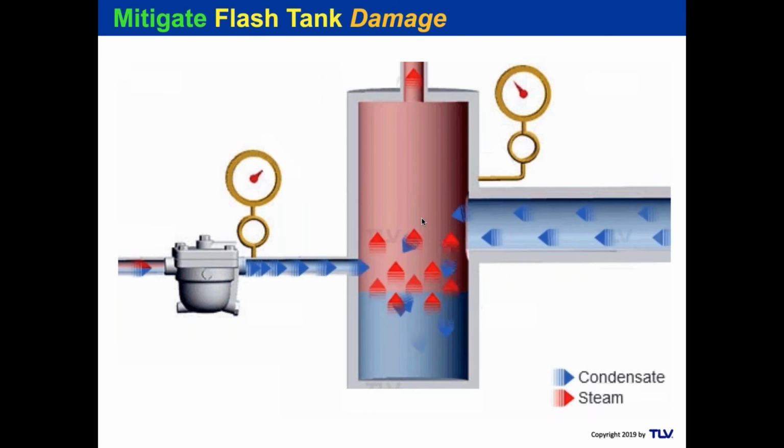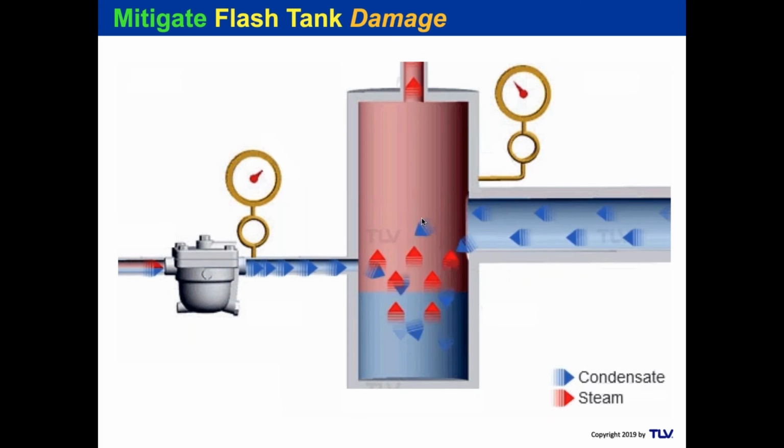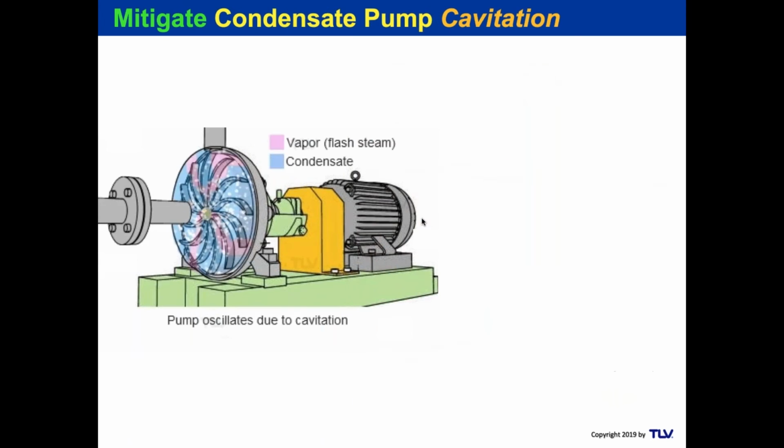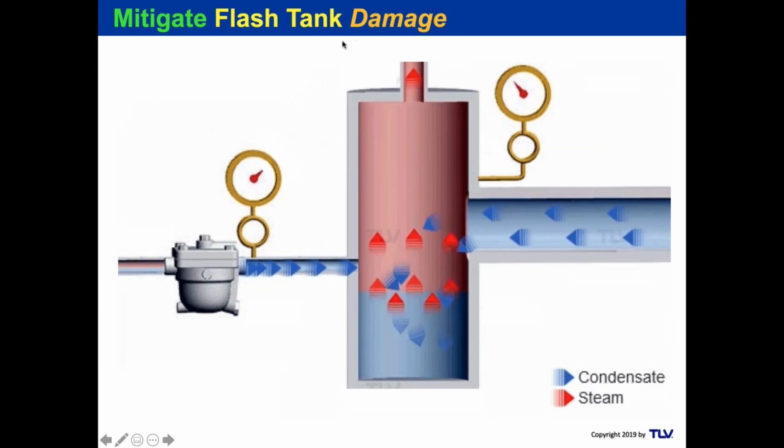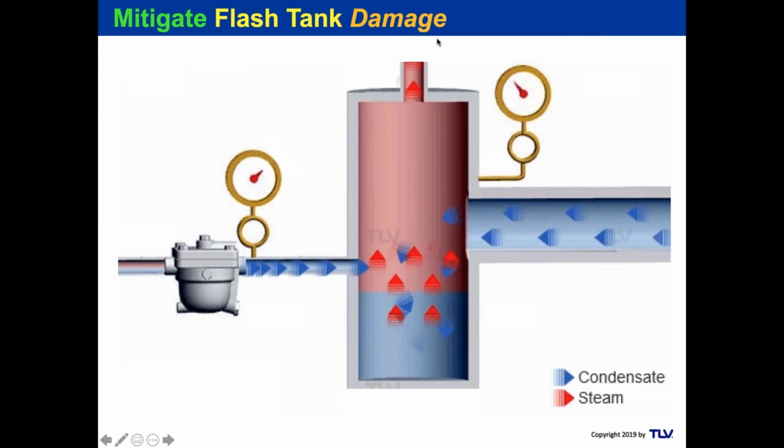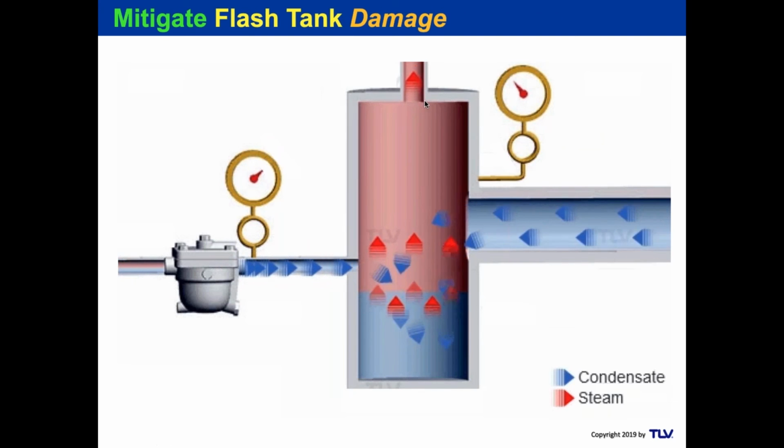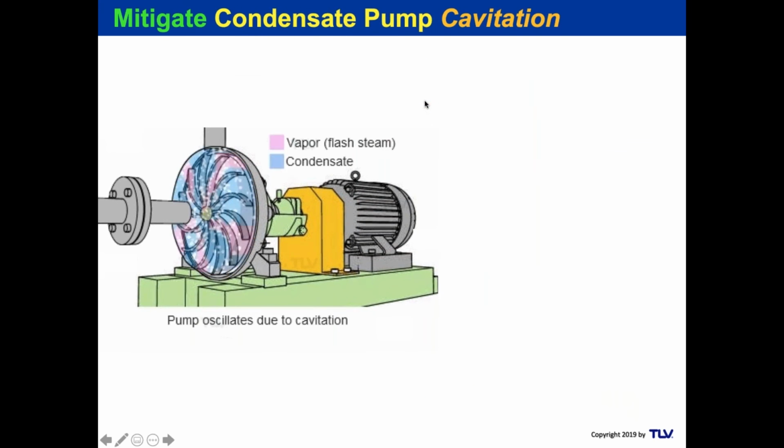It's nice when we can just get all the condensate coming in, no backflows, and just get everything coming out the top properly. If you can't get everything coming out the top properly and with low velocity, if you get high velocity coming out the top here because this is too small, well, then that creates a pressure in the system. And the pressure in the system elevates the condensate temperature. That means your pump set that is taking that condensate is at a hotter temperature than it should be.